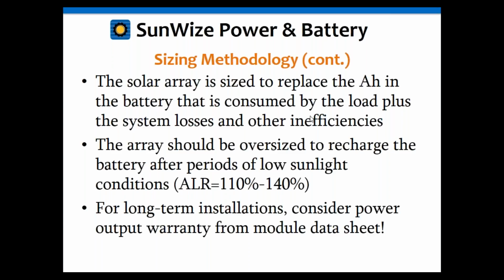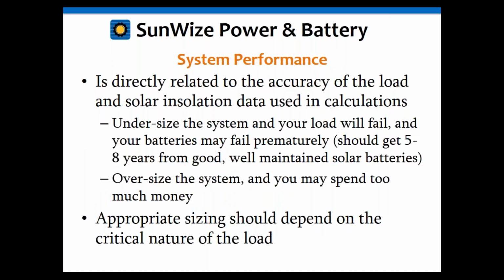So some people may put in additional losses of 20% because they want to have a 20-year design life to take into account the solar array, or they may add an additional 20% because of the battery degrading over time. So people may actually build into their derates and losses these types of things over time. So something to consider when we get into those losses, but just keep that in mind now. And along with that, perhaps just some of the warranties on some of the equipment too.